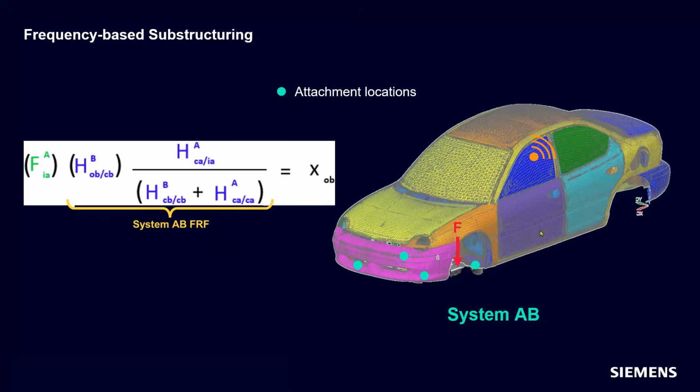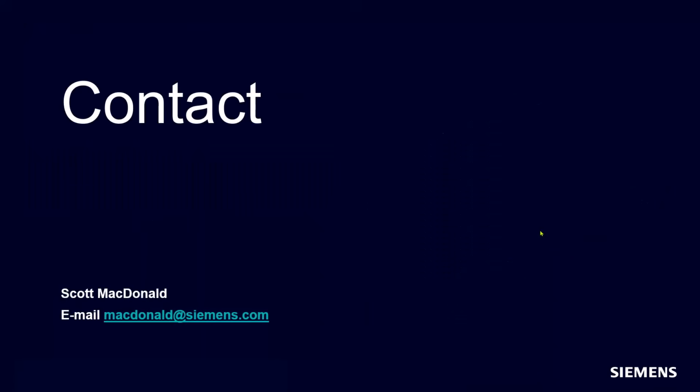So it's a very powerful tool. There's a lot of cool applications for it. Transfer path analysis and component-based TPA being one of the most popular. That is a crash course through frequency-based substructuring.